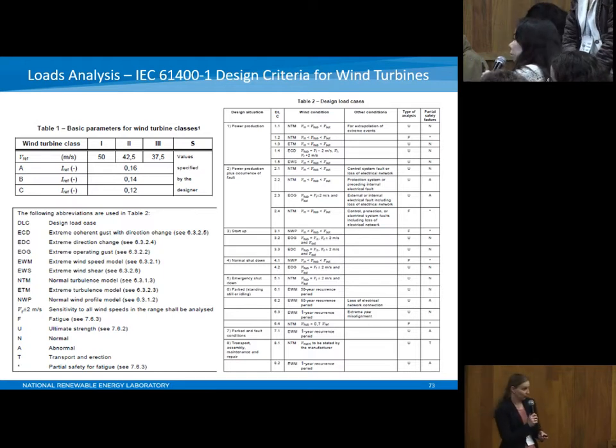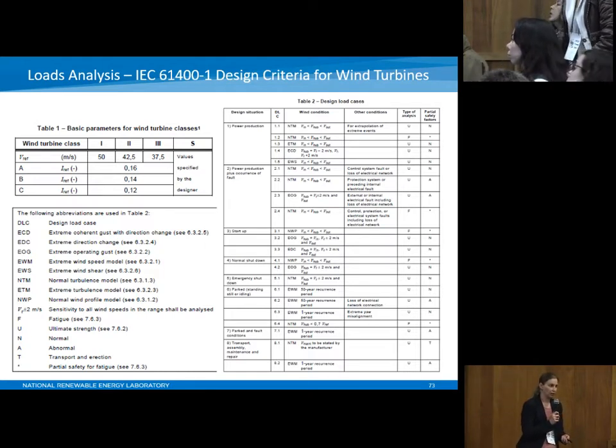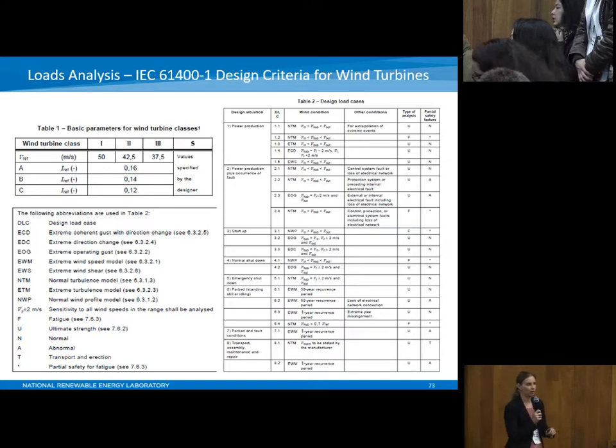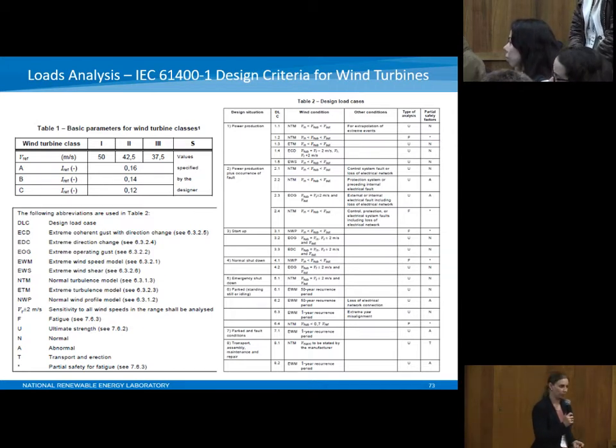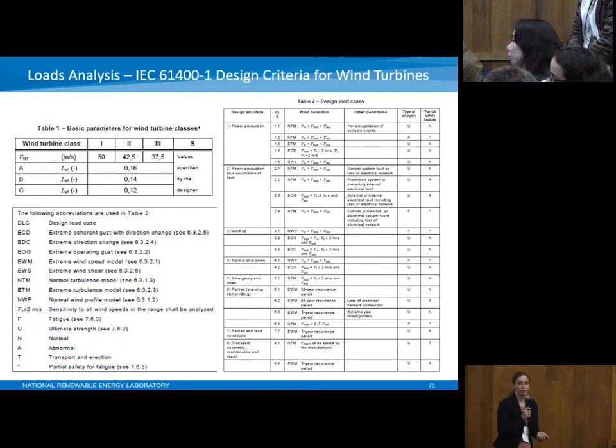So that is a great question. We've actually done some research looking at that. There's a few parks out there that have been built with different hub heights, and there are product offerings now where OEMs have moved to a product platform offering, where you have different combinations of diameters, generators, hub heights, especially hub heights. You'll have a number of them for different types of turbines. And so that begs the question, can I get better power if I use different combinations of turbine sizes in a given park? And so it depends a lot on the site resource characteristics.